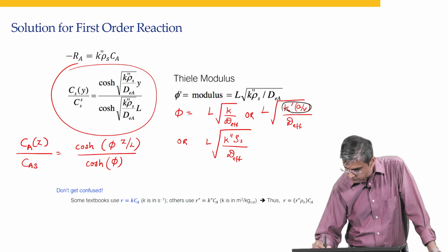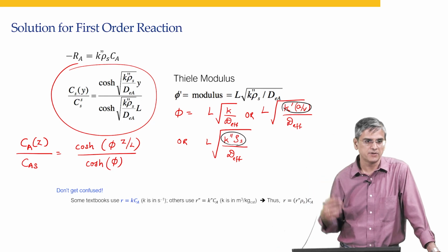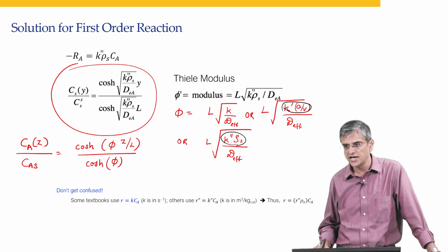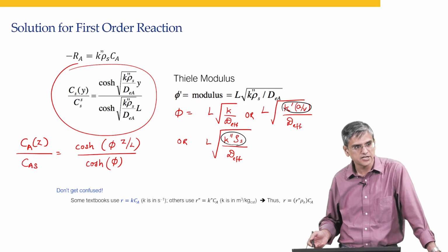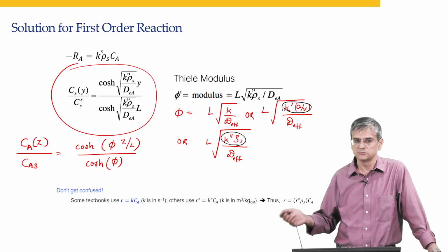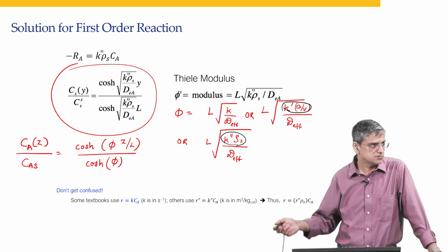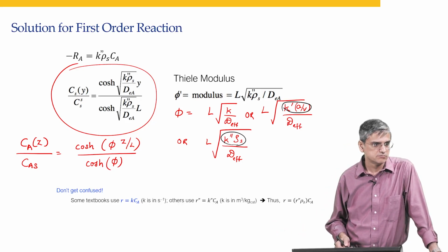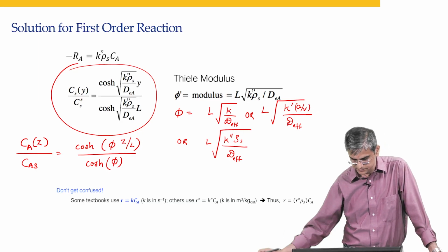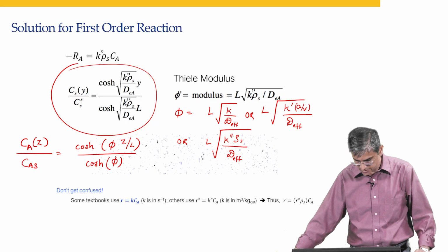Where do these guys come from? These guys do not come from module 5, they come right back from module 1. Kca or K dash or KVCa is the net rate of reaction in moles per second, which is equal to Ka Ca, K dash multiplied by A multiplied by Ca, which is equal to K dash multiplied by mass multiplied by Ca. We have gone over that a few times. So this is the expression that you are going to get.